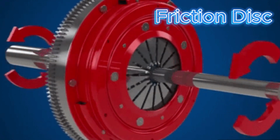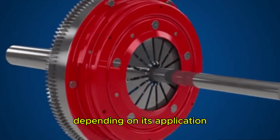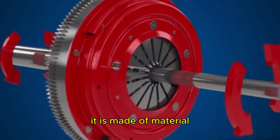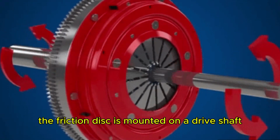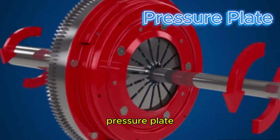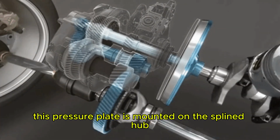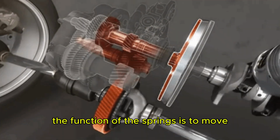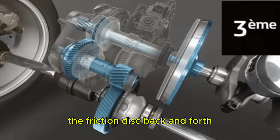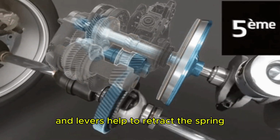Friction disc. The friction disc could be single or multiple discs, depending on its application. It is made of material with a high coefficient of friction. The friction disc is mounted on a drive shaft. Pressure plate. The pressure plate features another friction disc on it. This pressure plate is mounted on the spline hub. Spring and release levers. The function of the springs is to move the friction disc back and forth. Clutches use diaphragm springs, and levers help to retract the spring.